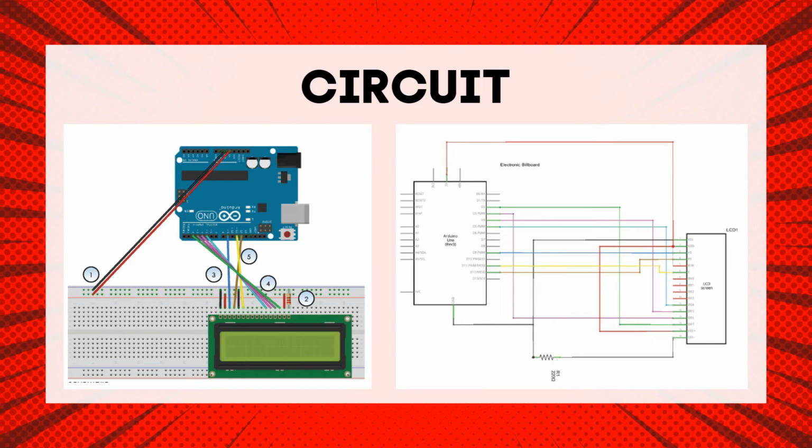Connect the 5-volt supply and ground to the power buses of your breadboard. We are going to connect LED pin 15 to the supply and LED pin 16 to ground in series with a 220 ohm resistor. We have to wire our 5-volt supply to VDD pin 2 and VSS pin 1 to the ground as well. Next, we're going to connect pin 3 to the Arduino's pin 9. This will allow us to change the contrast of the screen.